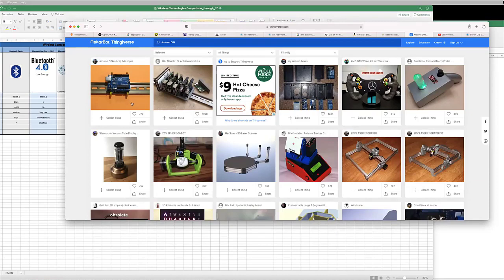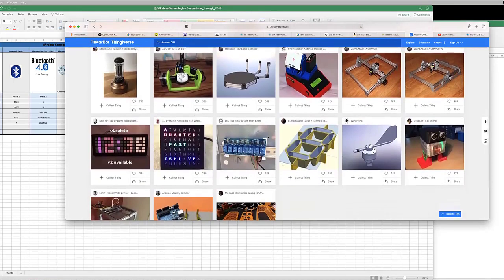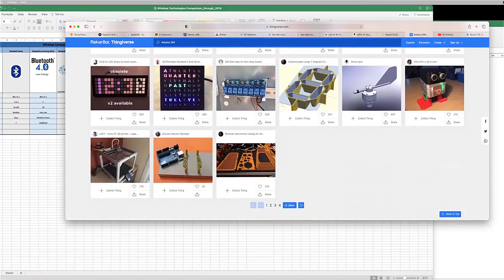And there's a lot of options available now for doing that, whereas previously you couldn't. So all sorts of stuff like that. One of the things that I'm often concerned with in industrial devices is what's called determinism, right? When you're doing publish, subscribe type things, you can guarantee that the communications is happening at some rate. And if it doesn't happen at that rate, it creates a major fault. So often, if I have devices out in the plant, I set them to 20 milliseconds. And that means I need a signal every 20 milliseconds, or I'm going to shut down. Something's disconnected, right?